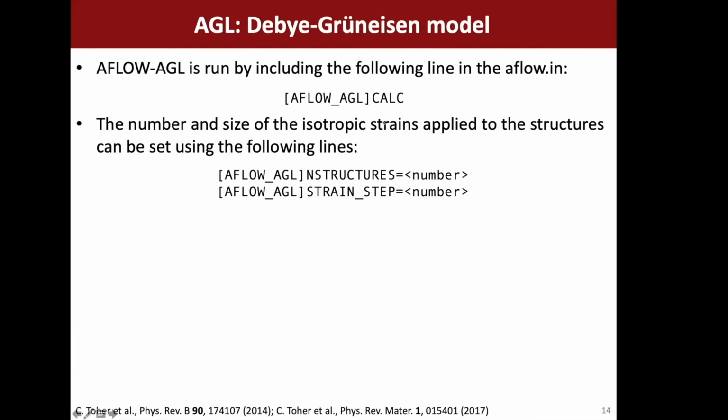Again, we can control the number and size of the strains that are applied. So the number of structures, then the strain step. Again, the default here is 28. The default here is 0.01, so 1% strain step.